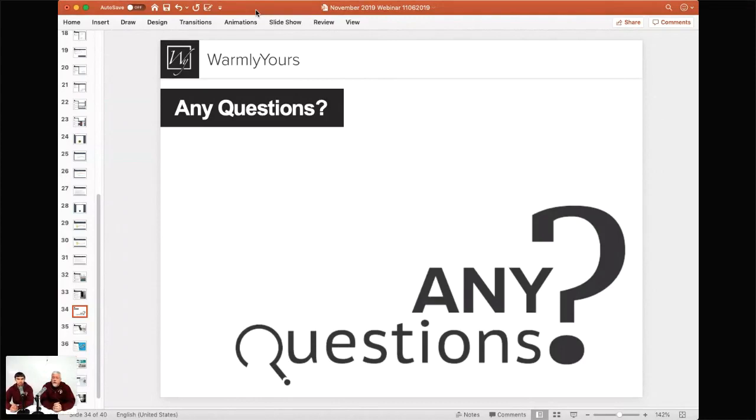Right. But the thing is, we could sit here for another hour, and I don't think we have time for that. I'm going to go through the common misconceptions about thermostats. One is that they regulate the temperature by regulating the voltage. They don't. A thermostat's either on or it's off. It's either feeding 120 or 240 to the floor, or it's off, not feeding power to the floor.